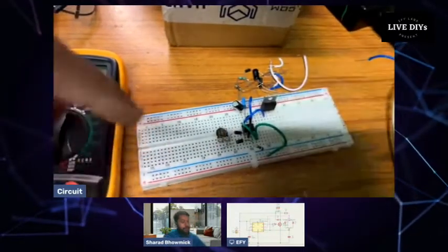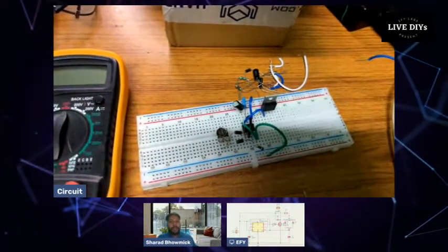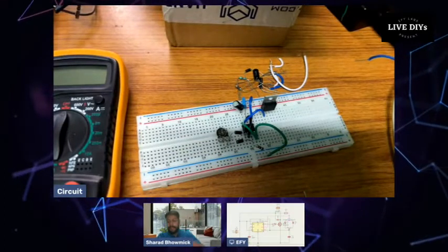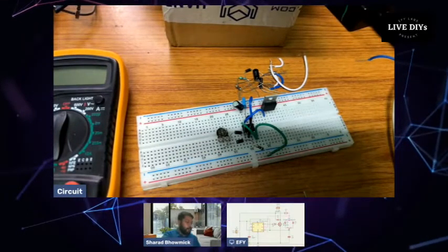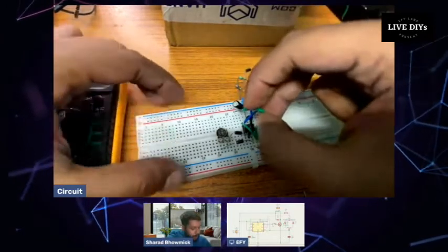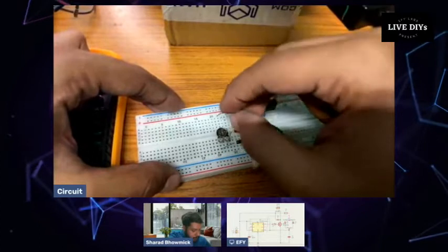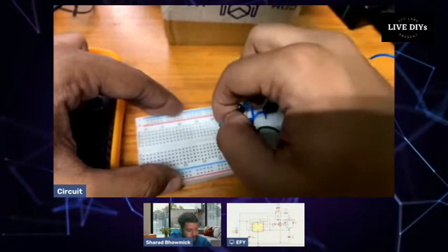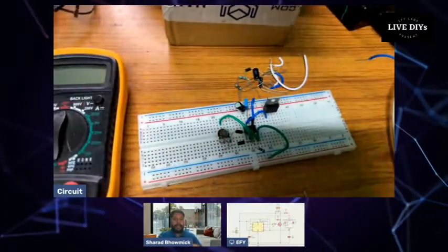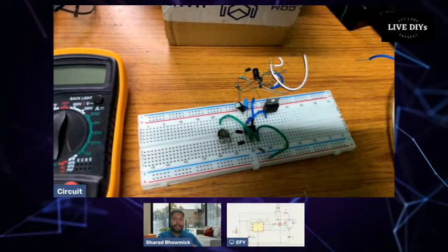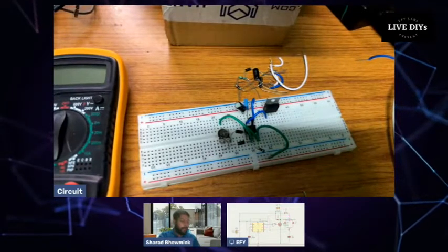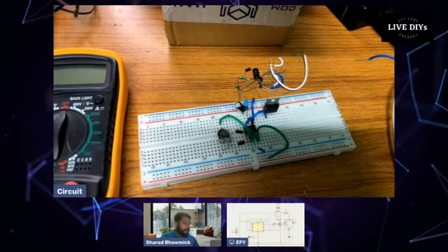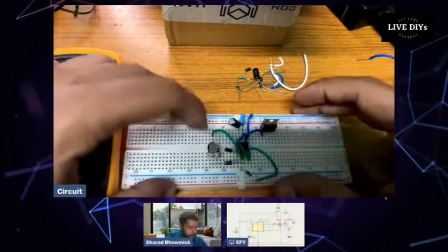so we have connected it with a potentiometer, and to control the potentiometer, we'll connect pin number 2 and 6 with it. So the output of the potentiometer is connected to pin number 6. Basically, we need to connect this whole segment, the potentiometer's output, to our capacitor for maintaining the charge or discharge time. So we have connected till pin number 7, and pin 8 was already connected. So basically our circuit is complete.